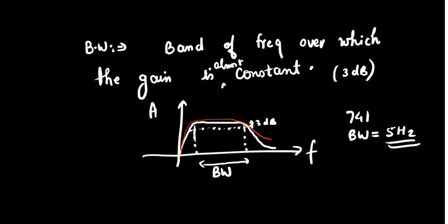No, it is not about log. I told you that this circuit is blocking DC, right? The circuit or the device whose frequency response is this, it is blocking DC. But our op-amp does not block DC, right? It passes DC. It also passes the low pass content of your frequency. This is a band pass filter type of system. Band pass filter means it passes a band of frequency and blocks a particular part on either side, right? This is called band pass.